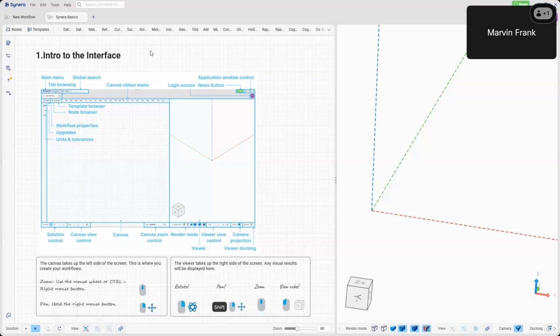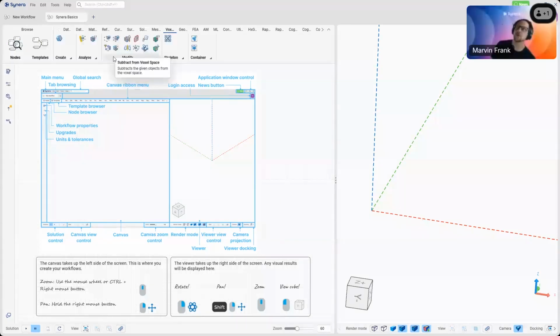So section for curves. When you extrude a curve, it can be a surface section. Then we have a mesh section, but that's not an FE mesh, that's a general geometry mesh. Then we have a very powerful voxel engine that is also used commonly for topology optimizations. For example, when the part is very tricky, you can voxel everything in seconds and then run the optimization on that mesh. That is very good to get a design proposal for the start. And then some geometry features, like intersecting things, Boolean differences, but also some fancy stuff like twisting or morphing geometry.